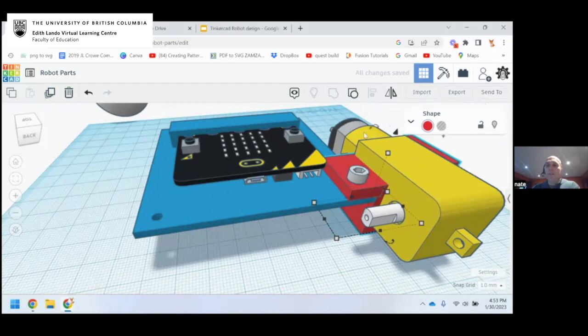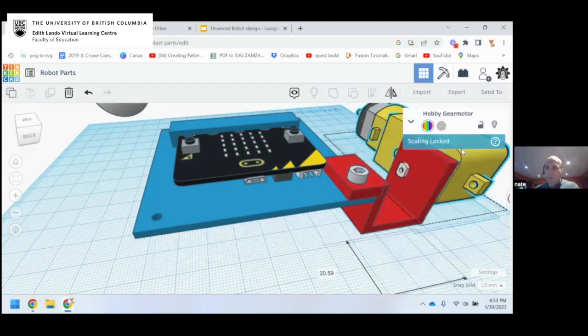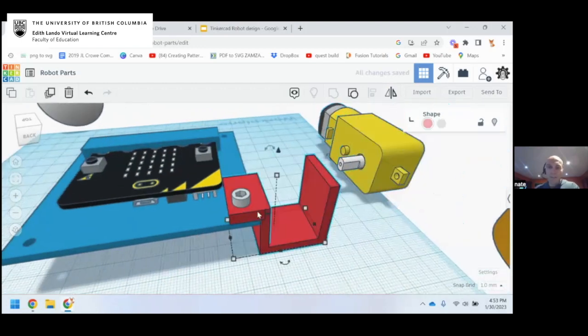But this time, let's use what's called a mirror. So up on the top, there's a little function. If I hit M on my keyboard, it will bring up a whole bunch of arrows. And you can see there's a bunch of different arrows. And if you hover over the arrows, I know it's a bit hard to see. You know what I'm going to do? I'm going to move this out of the way. It'll be easier to see. Let's bring this over. I'll click on it again. I'll hit mirror. And if I hover over the arrows, it shows you what mirror it is about to create.